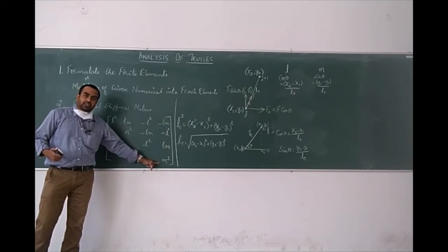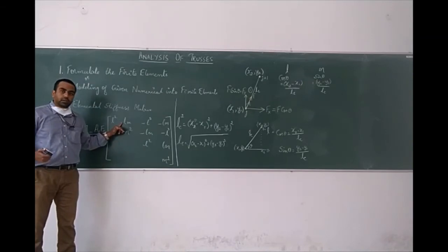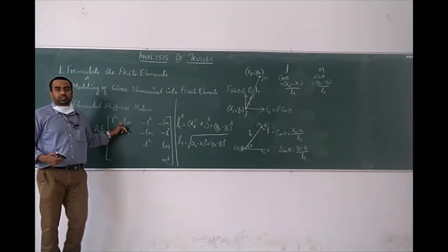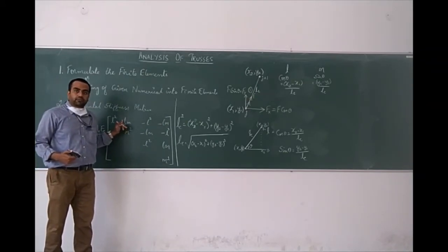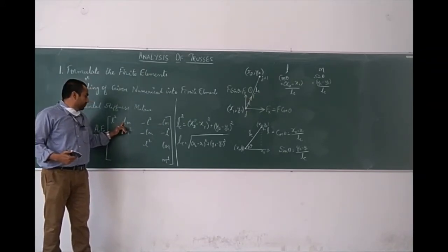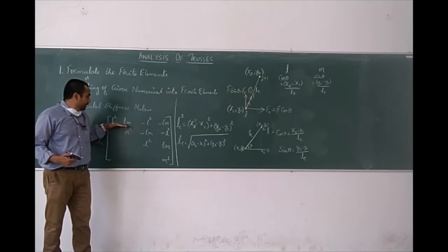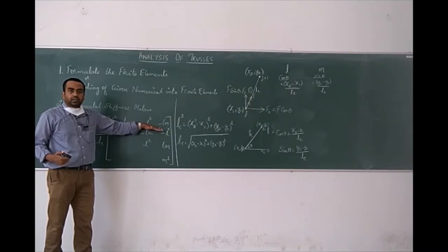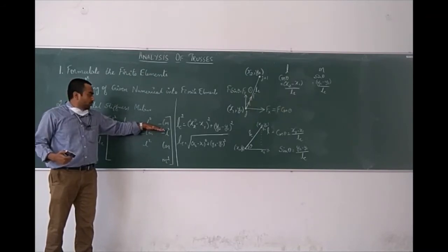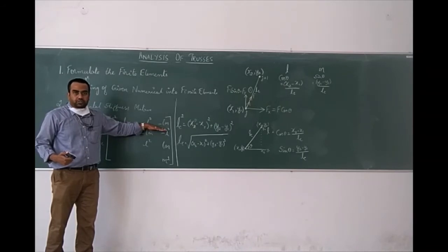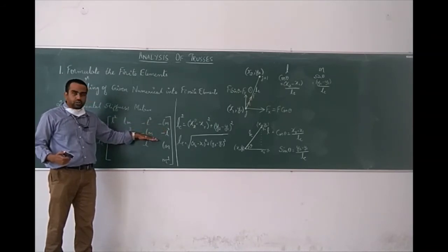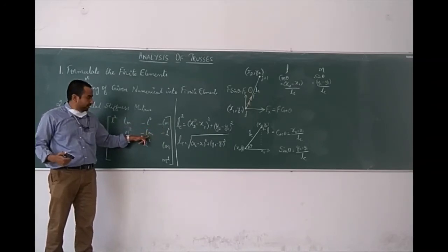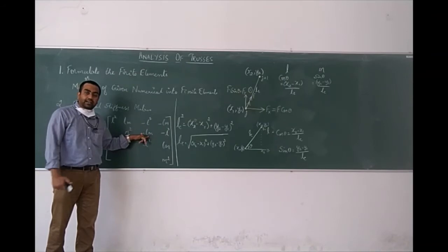Once the diagonal elements are completed, remember the product of both the directional cosines will be the second element in the first row. So once the second element is filled, the negative of the first two elements will be substituted as third and fourth element. Once you have done with the entire first row, coming to the second row, minus ln is present as the fourth element in first row. Repeat it in the other diagonal direction.